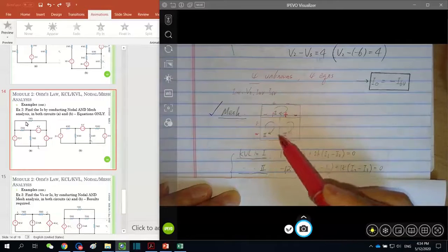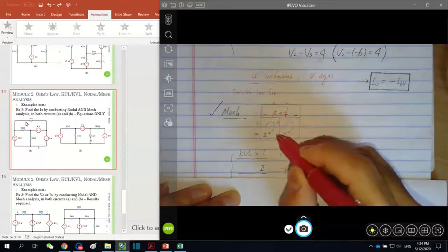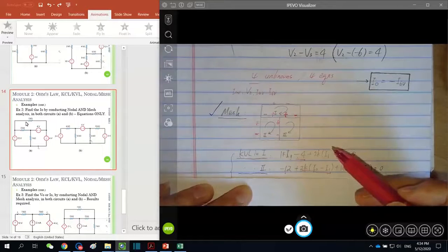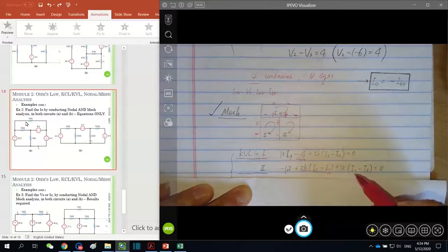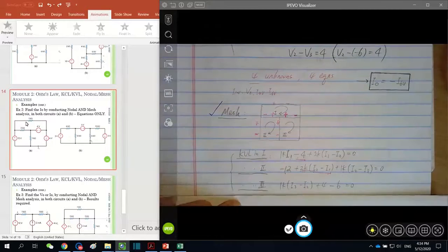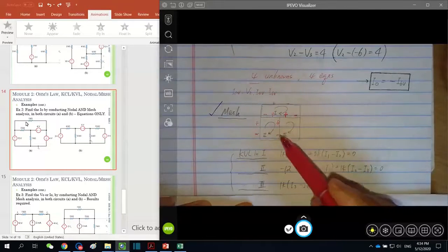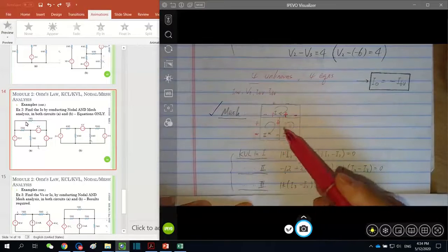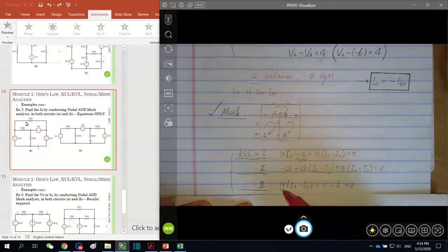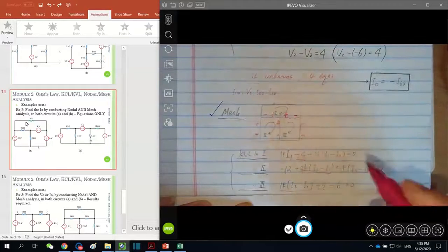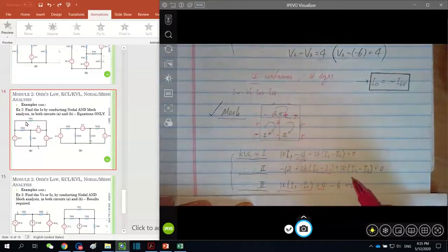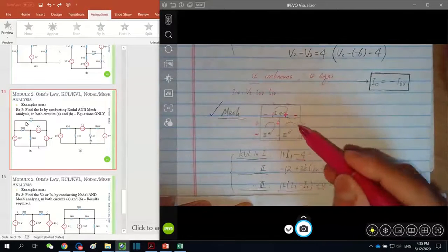Last one is the voltage across the 1 kilo ohm here. So again 2 currents with opposite direction, so it is 1 kilo ohm times I2 minus I3, equals 0. Similarly, we have mesh 3. So 1 kilo ohm I2 minus I3 is negative, or you can write it as 1K times I3 minus I2, same thing. Positive, negative 4 volts here, and then you have negative, positive 6 volts. Therefore, it's negative 6, since by the rotation direction, you come across negative first, followed by positive polarity.